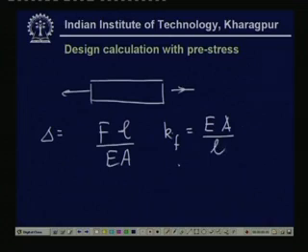But what about Kj? The calculation of Kj is very complicated. When you have a gasket joint, remember that there are other elements. If you consider the last example, there was the cover plate, then the gasket, and then this one.